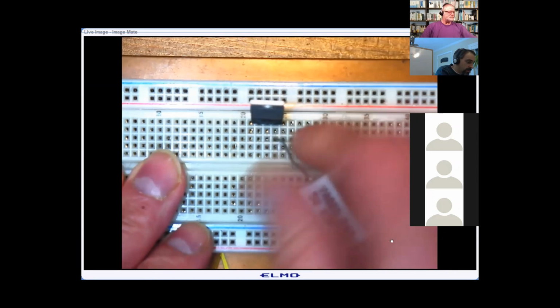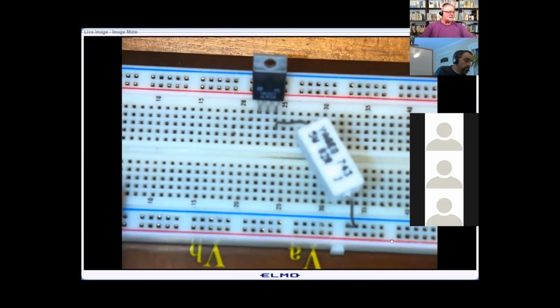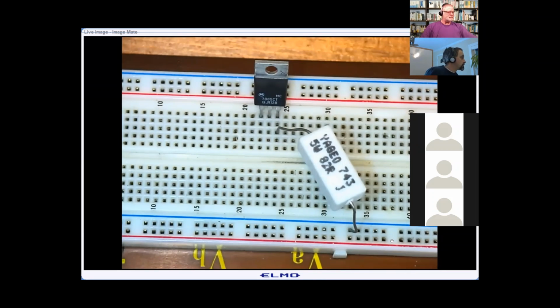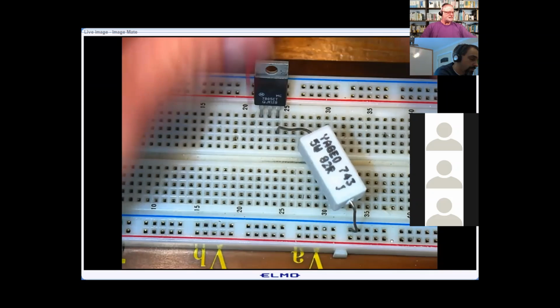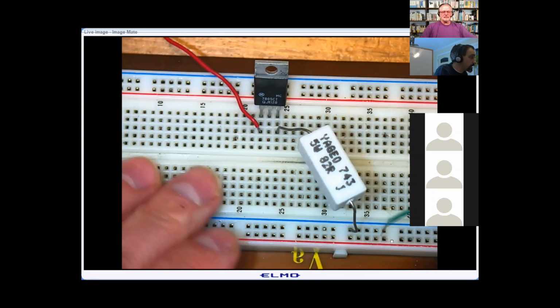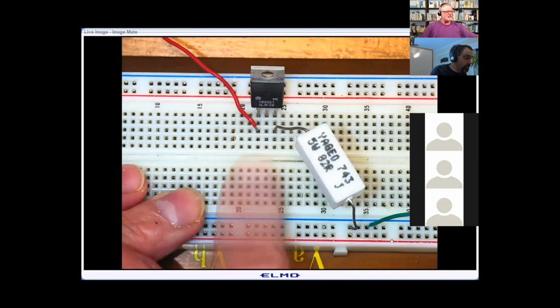Actually, I'm going to tie it to the third pin right there, just like that. I'm just going to bring them down a little bit so you can see it. Bring this up. Is that better so you can see all my wires? Okay. Our VIN is going to be 20 volts. We're just going to keep it at 20. So all I'm going to do is bring the VIN. I've got my power supply shut down for now. My ground, I'm just going to ground it down here. But now notice that I need to take this middle one and bring it down too.